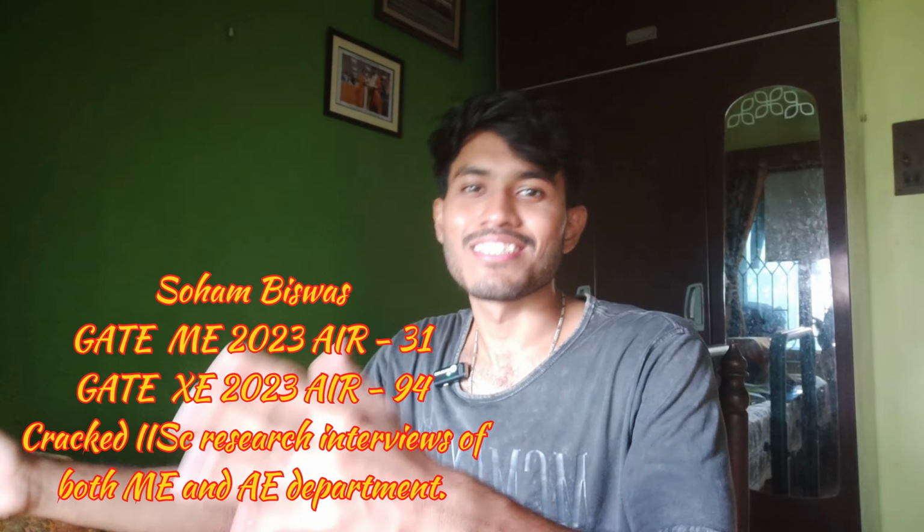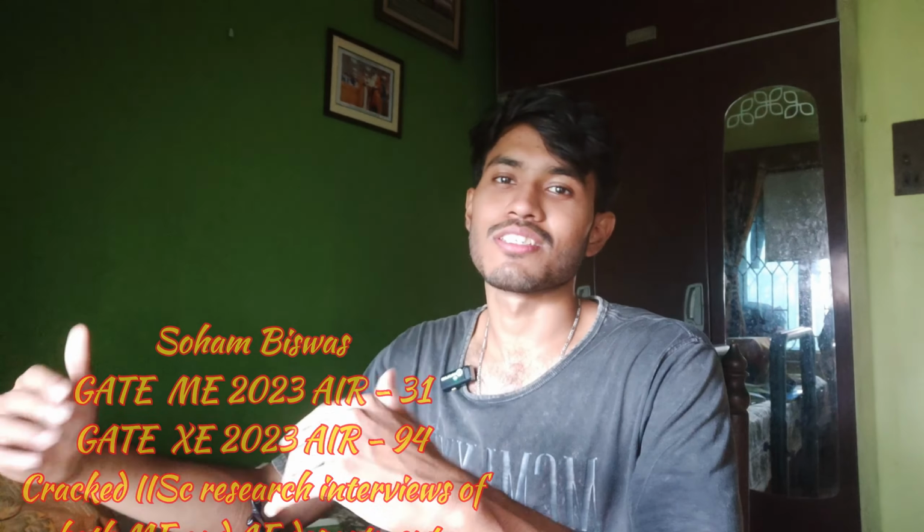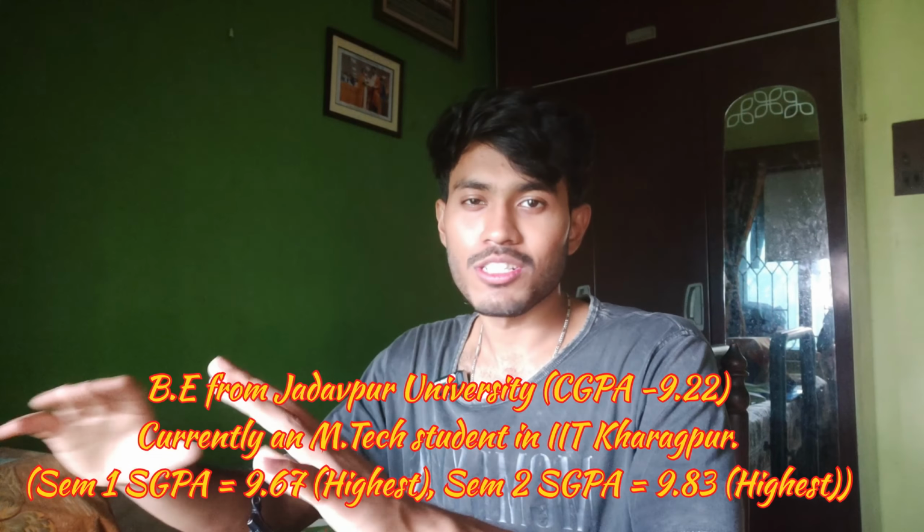So I talked about the scariest things already: the Bessel function, the separation of variables, the method of superposition, all these things. And I have already ended the chapter on fins from the point of view of advanced conduction. I have also talked about the basic definitions for fins, that is fin efficiency and fin effectiveness. So today, let us firstly meet another form of Bessel function, how it looks, and also some graphs of Bessel function with which you must be acquainted to be able to solve problems in your examinations.